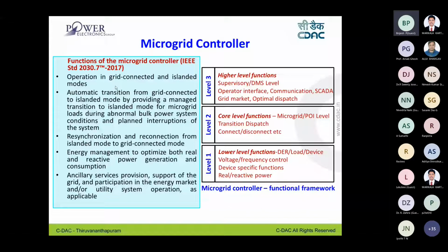Either you can do a forced isolation, or you can schedule an interrupt, or isolate your microgrid based on your grid conditions. All of these are possible with the microgrid manager. Then resynchronization of the microgrid with the PCC is also managed by the microgrid manager. So these are the functionalities of a microgrid manager.